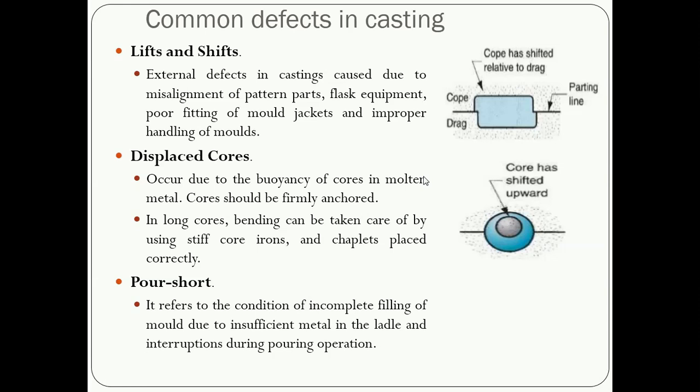This is also a major defect. It also has no kind of remedy. So to the extent possible we have to avoid this defect. That is, lack of molten metal inside the ladle, so incomplete filling of the mold cavity takes place. That defect is called a poor shot.